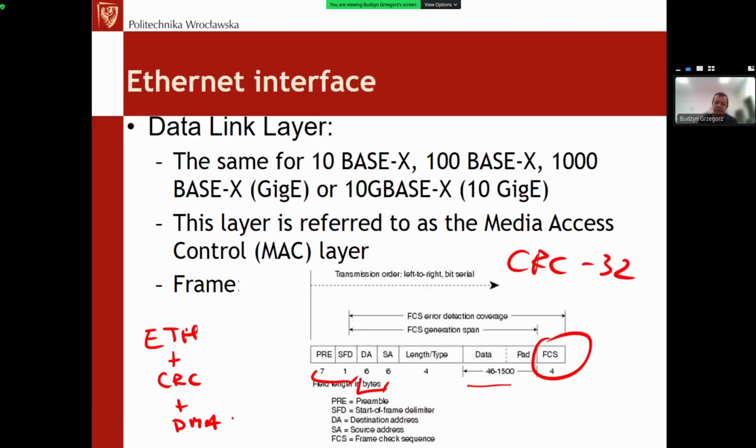So usually it goes together. Usually we have all 3 things implemented and present inside the microcontroller, so that we can construct a fairly fast and efficient Ethernet communication subsystem. But still it may happen that some of these elements are missing, then it's a no-go area. So never try using Ethernet, or be extremely cautious with using Ethernet without either CRC or DMA, or both.